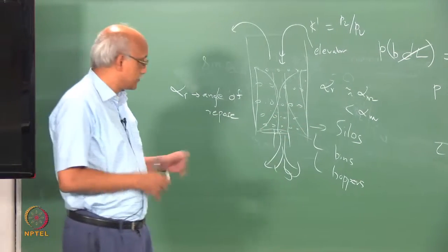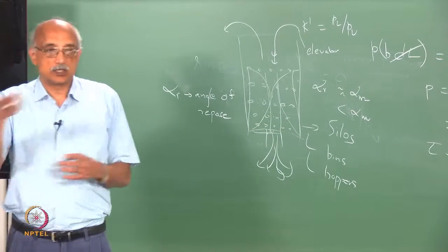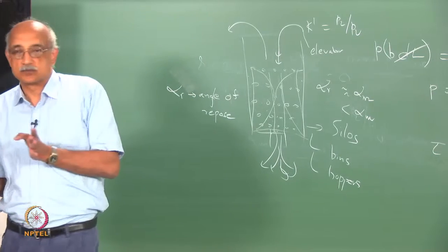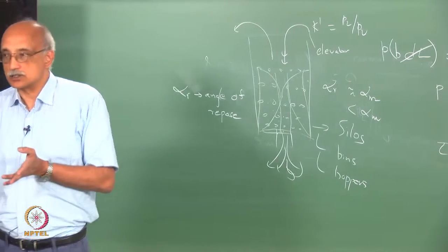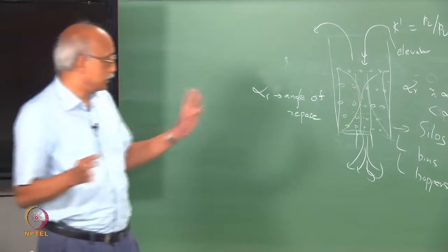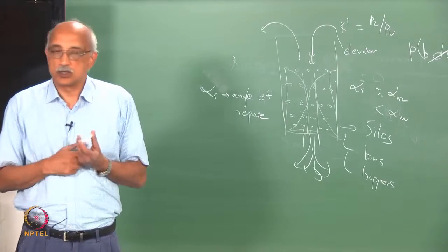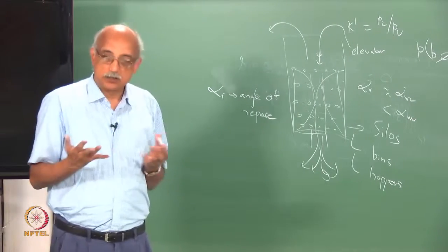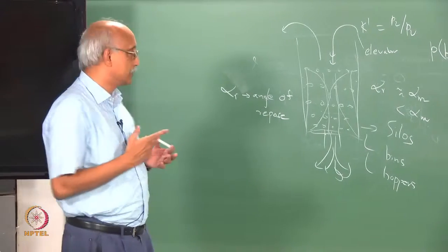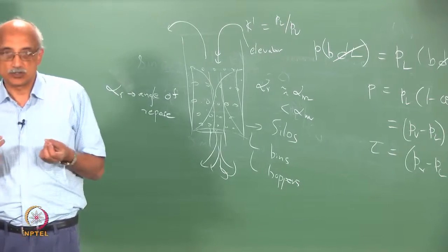Sometimes the central column will discharge, but if the connectivity to the rest of the material around it is poor, the discharge may stop at that point or become intermittent. So, one of the key things to look out for when discharging material from bulk storage is whether you are getting continuous flow. If you see a pattern of high flow rates followed by low flow rates, then you know that the discharging process is not working as well as it should.